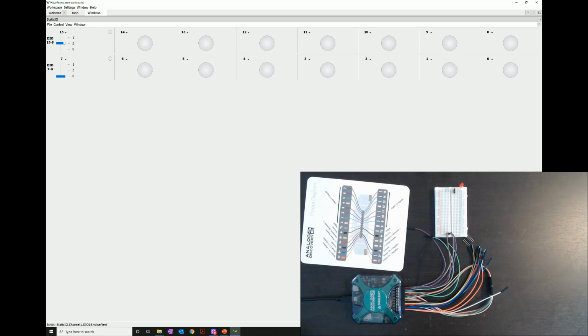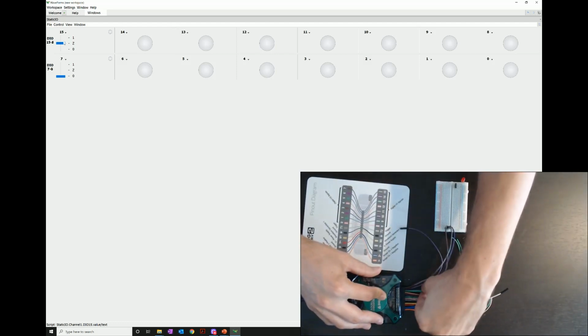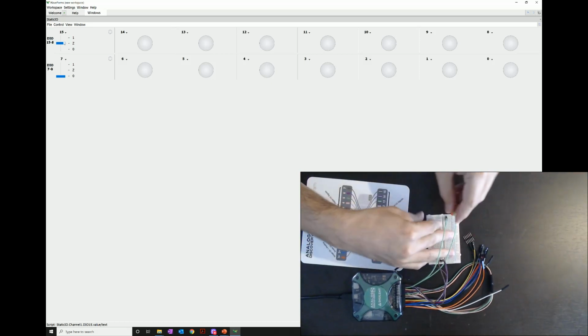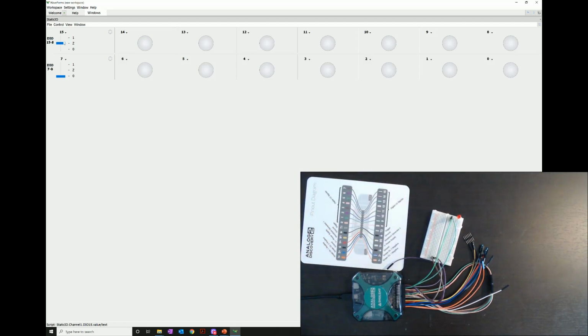Looking at our LED here, we see the cathode as the wire nearest this flat edge. This is usually the shorter wire. The other wire, usually the longer wire, is our anode. So let's connect our anode to pin 5 and our cathode to pin 13. In WaveForms, we can now set both of these pins to push-pull output switches.